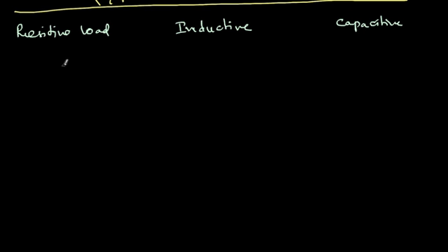V1 equal to E1, and luckily we don't have any I naught current here. So I have E2 here. Now because it is a resistive load, I2 is in phase with E2, and therefore I2 dash is in phase with V1, and this itself is the vector diagram.